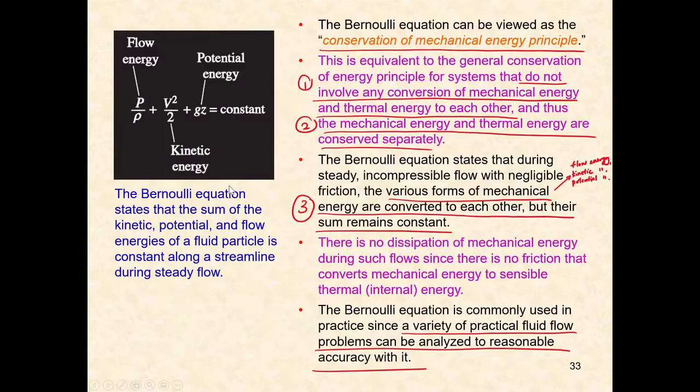Let me repeat again. The Bernoulli equation states that the sum of kinetic, potential, and flow energy of fluid particles is constant along a streamline during steady flow. The energy might change from one form to another, but the total sum, which we call mechanical energy, is always the same. We can view the Bernoulli equation as a conservation of mechanical energy principle.